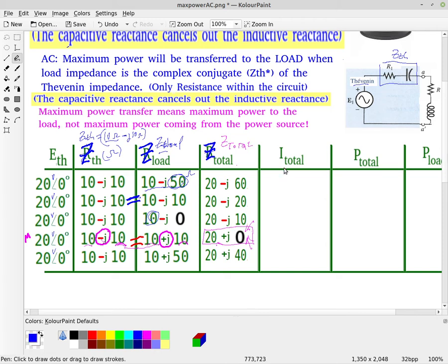And so we're going to calculate the current, all right? And if we calculate the current, that's just Ohm's law. So we're going to take the voltage E Thevenin, which again does have an angle to it. It's a phasor, it has an angle, right? But I'm using it as my reference, so I'm using an angle of 0. And we're going to calculate our current then. So it's E Thevenin divided by Z total. That's going to be my impedance.